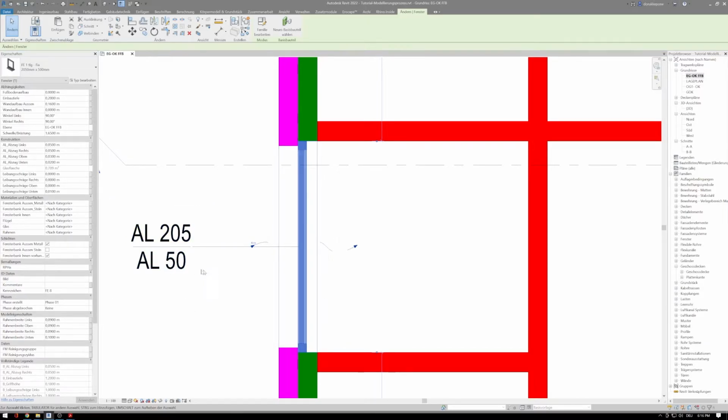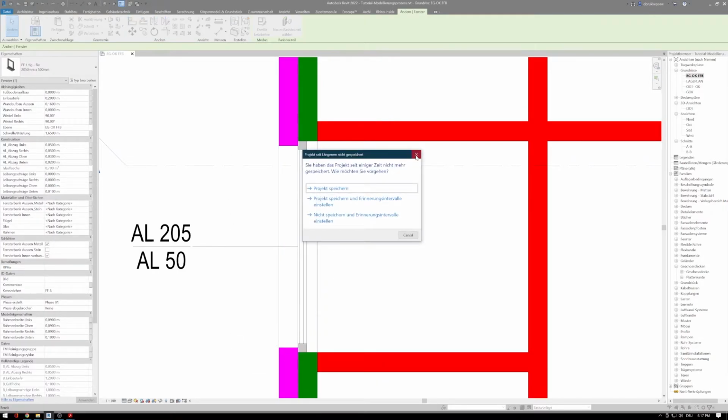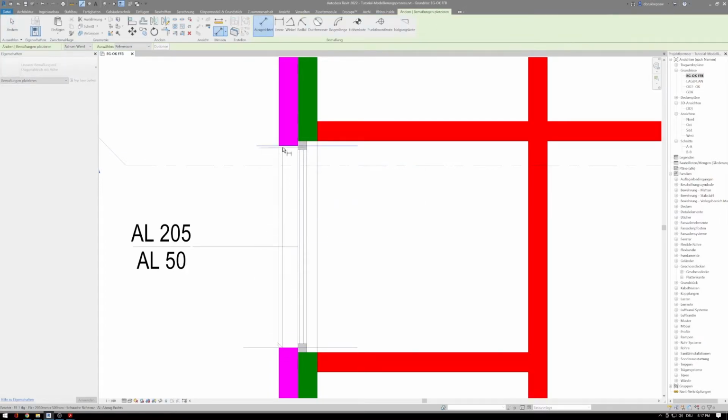Now, I want it to be clear. The reason it happened is because of these Abzug links and Abzug rechts. As you see, my total Abzug is 5 from each side, which makes it 10 centimeters. So it has 10 centimeters cut from my main width. So I go DI for dimension, and I check my dimension in between, which is 2.05. But the main width is 2.15. That's why we have to arrange the Breite, aka width.